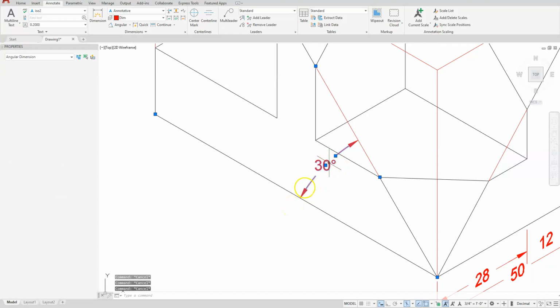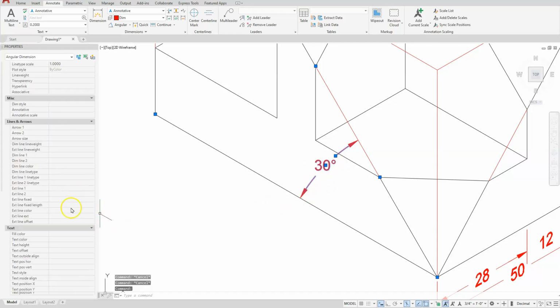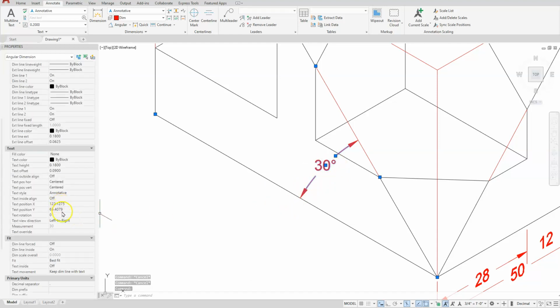You can go ahead and select your text. Come down to the word text. Your rotation angle, set that equal to 30, and you can see that this one goes the other direction. So I'll type in -30. Then you can choose which style that you want to use, ISO 1 or ISO 2. And in this case, ISO 2 is the one that I'll choose.